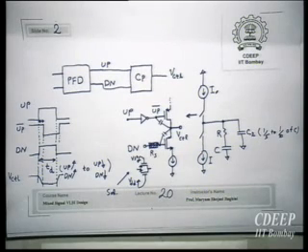Why is it not stable? You mean that during this time the frequency will change? You know what happens? Practically it creates a phase offset. You will see a phase offset between input and output, the output of the VCO and the input phase. In practice, that leads to that phase offset.